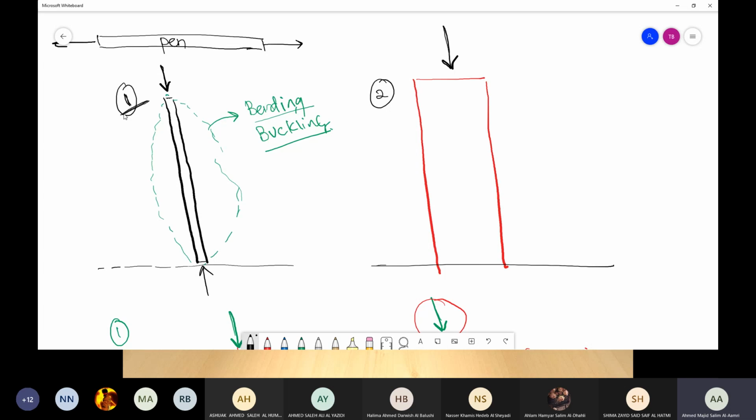No. Okay. So when I refer to buckling, it's not only about the length, but two things should be taken into account. One is the length, one is whatever we call the cross section. That's why in your design of structures 1 or design of structures 2, whenever you checked for buckling, you have taken L divided by a certain side. So it's not only length, but length and cross section. If the cross section is huge, it will not buckle easily. If the cross section is small, you will see that it's easily buckling.